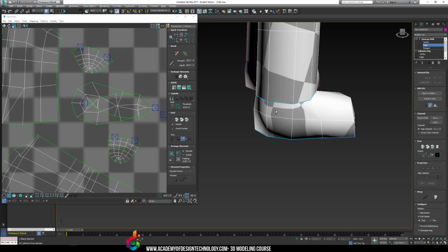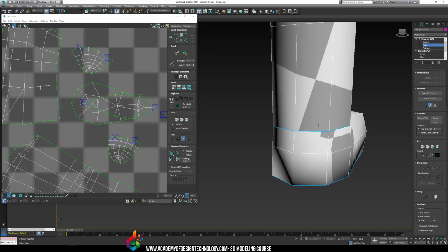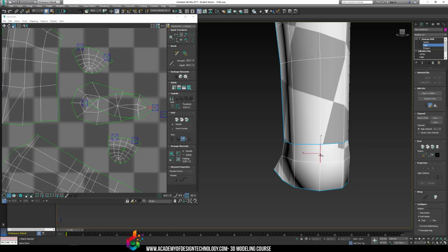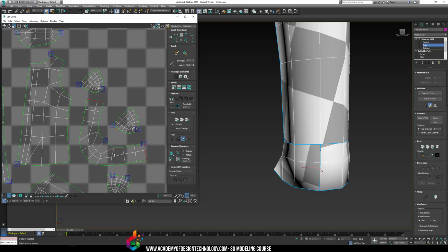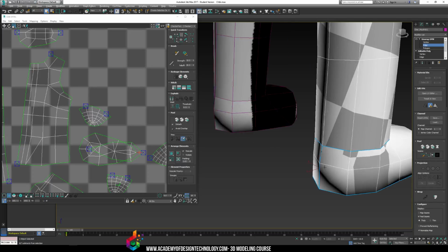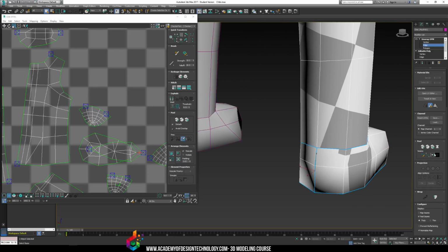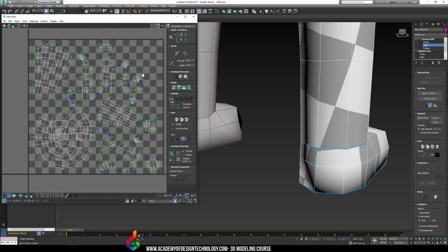So I'm going to create a couple seam lines here in the back. Maybe even just one seam line in the back might help. Let's see. I'll take the back of the foot here, convert that edge to a seam, and look how much better that looks. Watch, undo. That's what my foot looked like. I added a seam line down the back of the foot. I convert edge to seam. Make sure this blue line's here. And that looks much, much better.